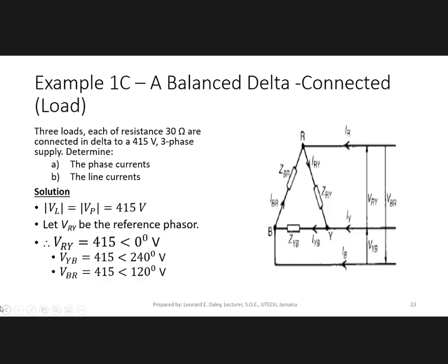Remember, a balanced system is going to have 120 degrees between the phasors, right? So they are going to be located like this. So the angle difference in the star system is the same that we're using here. It's just that the subscripts now are different.